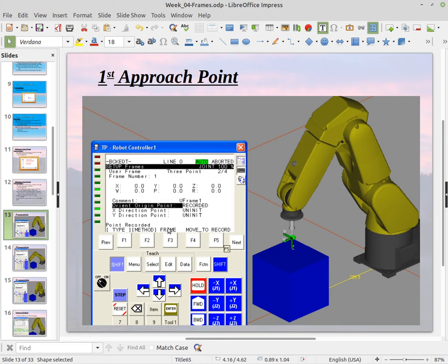So remember that the world frame, like here's axis 1 between the yellow and the gray, and here's axis 2, which is the second axis that can rotate. So if I was able to draw a straight line up through the center point of axis 1, and then horizontally through the center point of axis 2, my origin point would be here somewhere back behind the robot. That's the world origin point. That's the focal point for the robot.